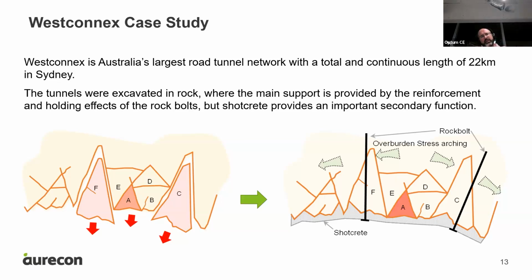One of the things we do a bit conservatively here in Australia is that when we are factoring fibre reinforced concrete, we're still treating it as plain. We could be a bit more aggressive, but we decided to be on the conservative side. We apply reduction factors to the strength that are the same as plain concrete, so we use a reduction factor of 0.6. Yes, those are comparisons that were unfactored. We just wanted to show raw numbers so we can get an idea.